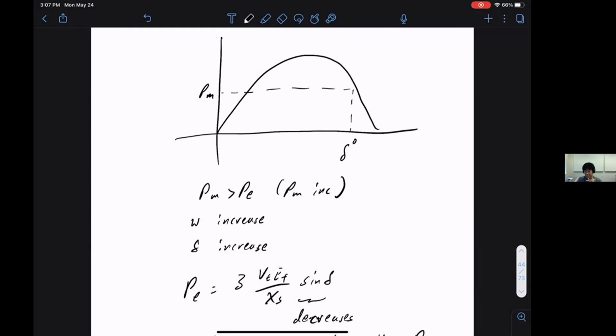So in the first case for the stable operating point, the angle will be slightly closer to 90. Would you then try to compensate to bring that back down so you don't get too close to 90? No, you don't bring it down because that may not be possible. In practice, you have a constraint such that your angle is far away from 90.